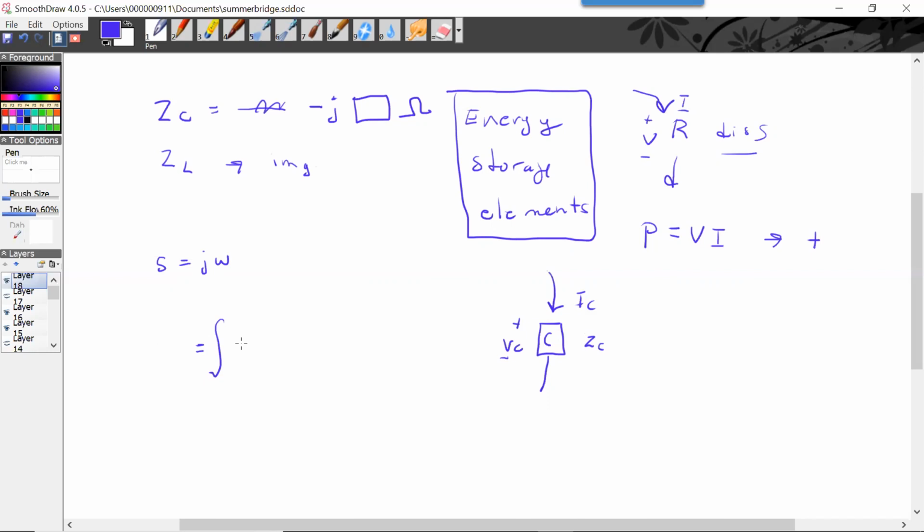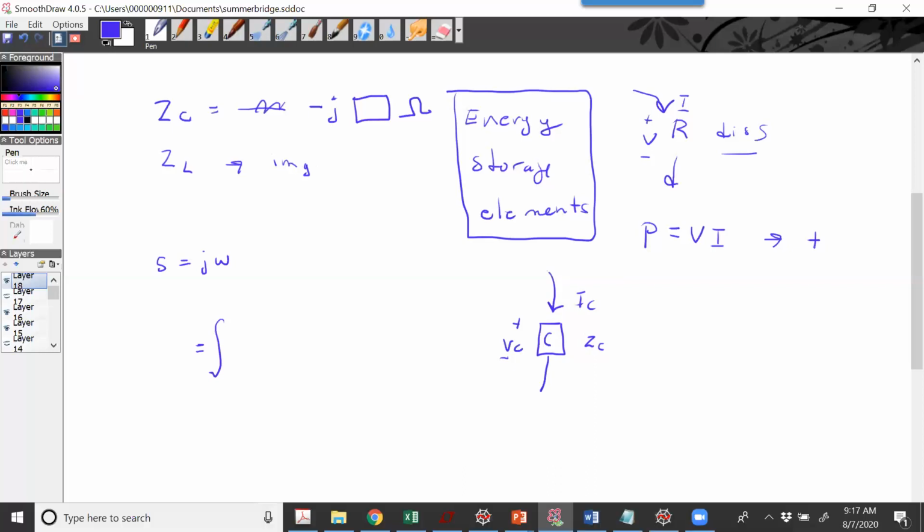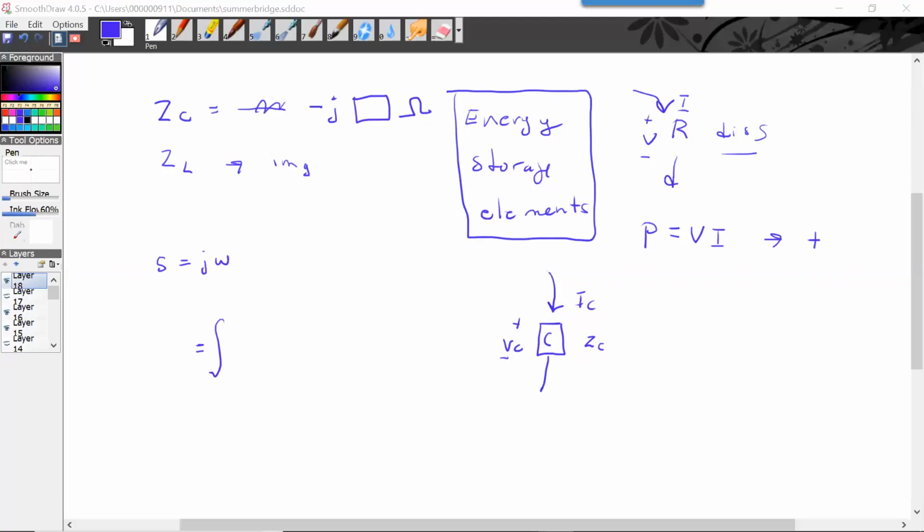Because I have to show you truthfully, the reason we could derive it mathematically, but the real reason is that capacitors store energy in terms of charge separated by a plate, and inductors store energy by charge moving back and forth. And because it doesn't dissipate, it's really just storing the energy. That's why it's imaginary. Is that good enough, Luca? Okay, thanks. Because, yeah, sometimes I can go off the deep end when I'm answering a question. Any other questions?